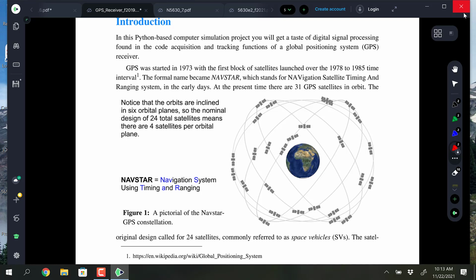Whoops, that one just went away. It's now trying to find this satellite. I mean, you have to be patient. So it has a display where you can see bars, signal strength, and it'll have filled bars, meaning it's locked onto those, and then it will have clear bars, meaning that it knows from ephemeris information that these satellites should be reachable, but it hasn't locked onto them yet. So you just watch it kind of unfold, and then when it finally has enough satellites, you can switch the display to the map view, coordinate view, whatever, and then you can get your coordinate.